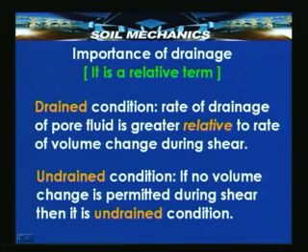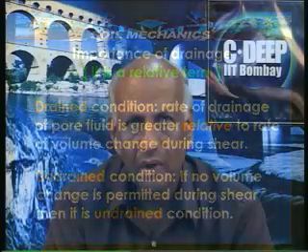On the other hand, if I say that the test is conducted under undrained conditions, it could mean either that there is no passage for the water to go out, or that the shearing is done so rapidly that water does not get time to get a free passage out.